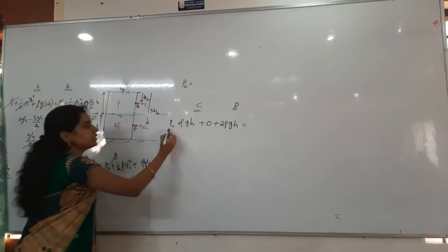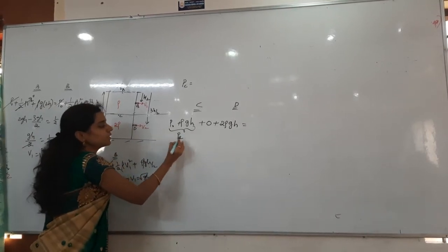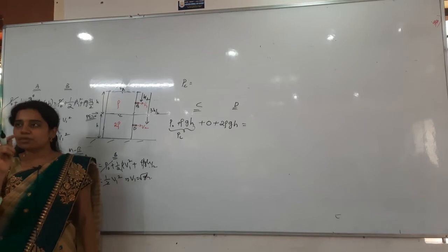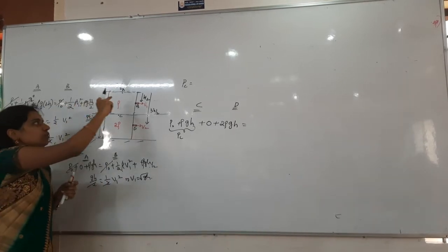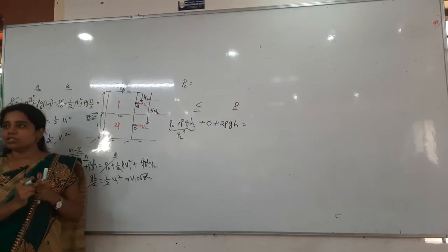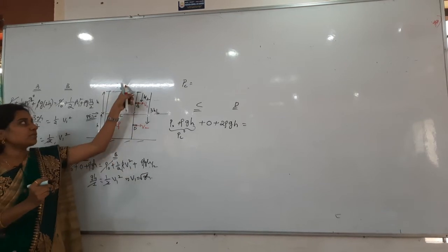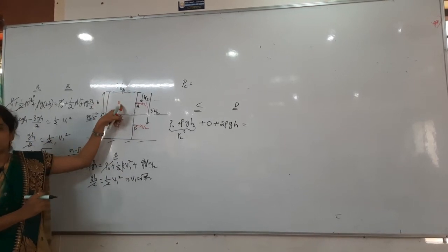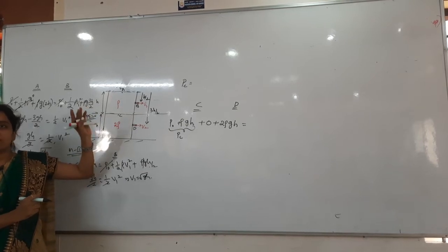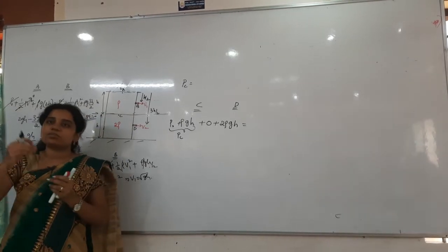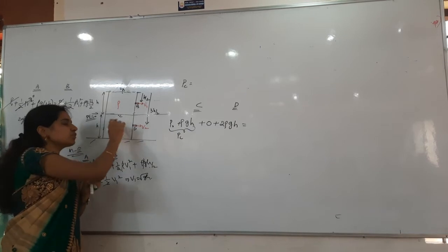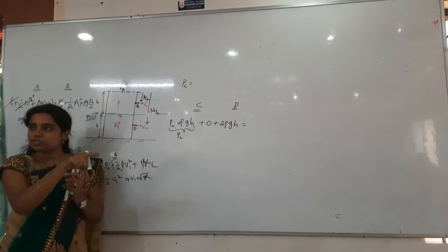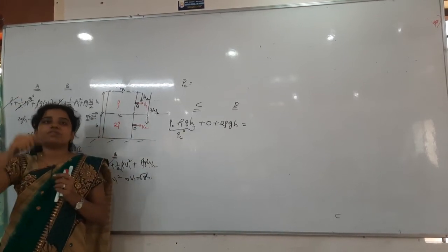Here this is entirely the pressure at point C only. The point C is bearing this much of liquid weight above it. So the pressure is atmospheric pressure plus the height of the water column with whatever density we are having. That is not saying it belongs just to point C, which belongs to 2 rho only, but above that which density is there?